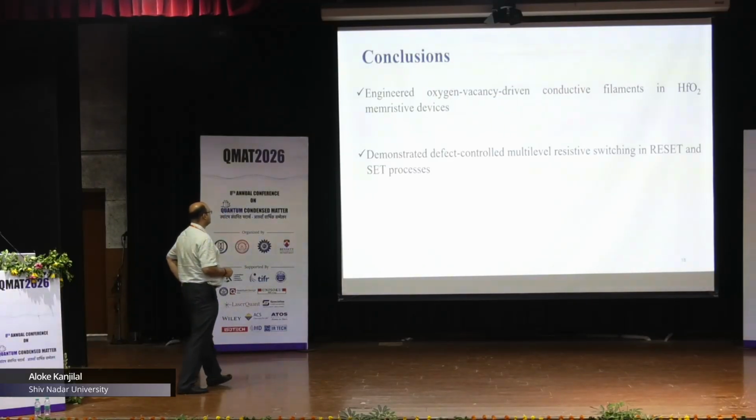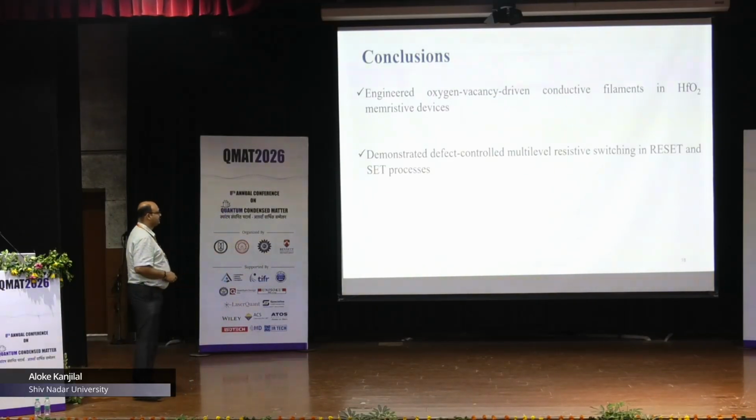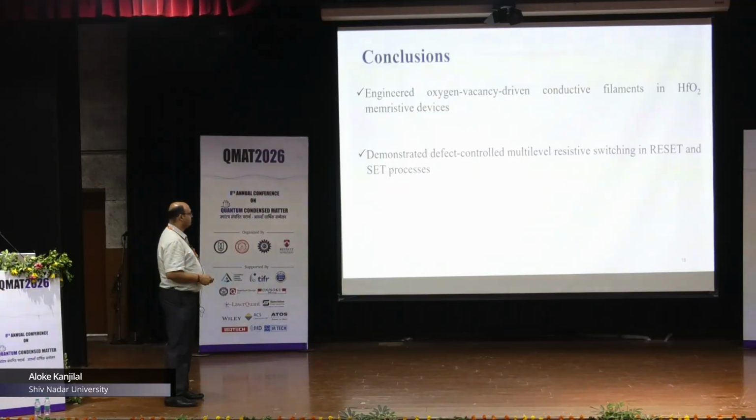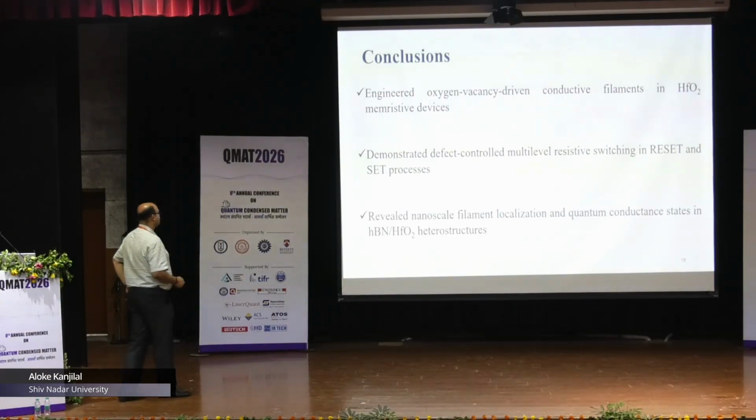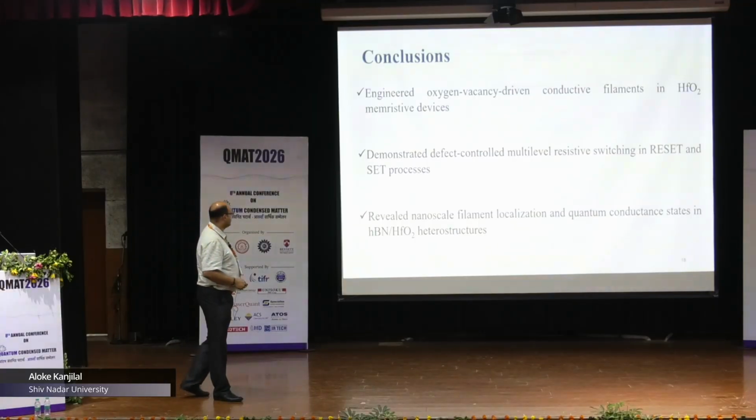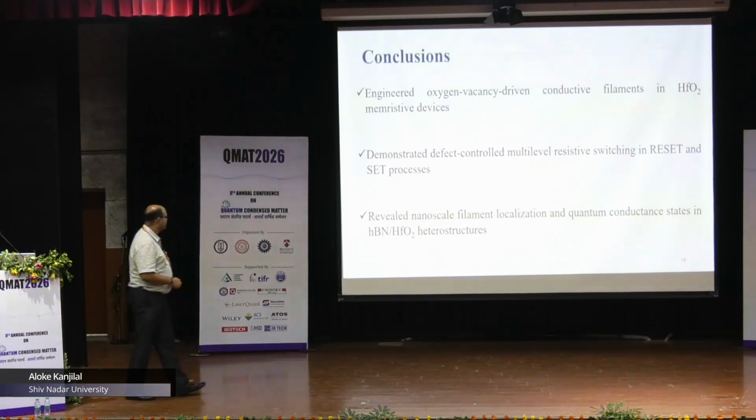Secondly, I demonstrated defect-controlled multi-level resistive switching behavior: in reset when the potential is changed, and in set when the compliance current is changed. And thirdly, I revealed the nanoscale filament localization and quantum conductance states at the edges of the hBN flakes in the hBN/hafnium oxide heterostructures.